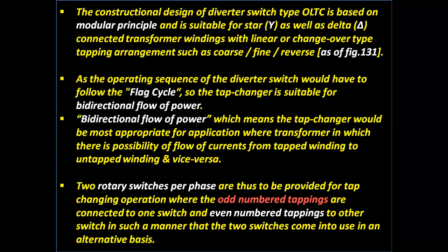The constructional design of the diverter switch type OLTC is based on the modular principle and is suitable for star as well as delta connected transformer windings with linear or changeover type tapping arrangement such as coarse, fine, reverse, as of figure 131.